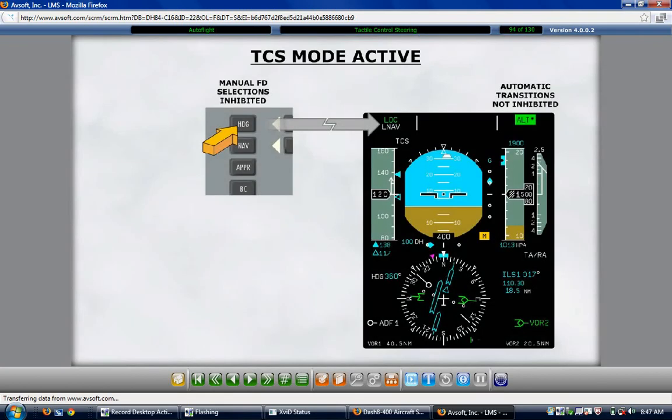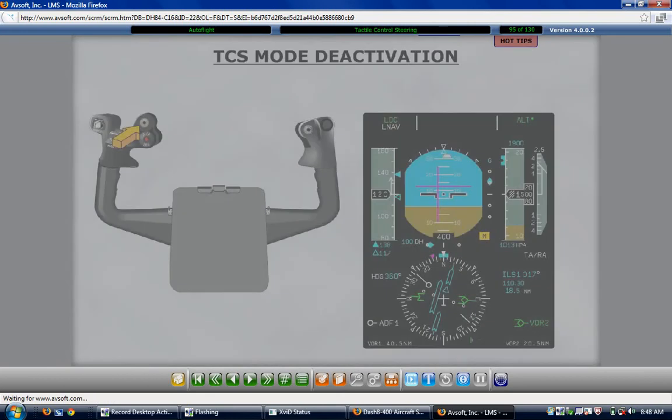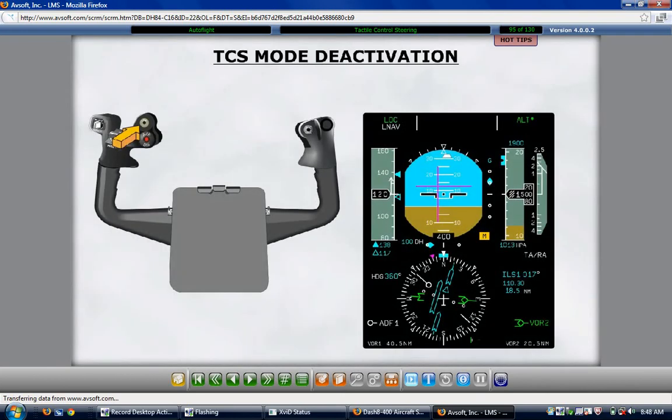The autopilot couples the flight director commands to the flight control surfaces using pitch and roll servos. The autopilot is engaged by pressing the autopilot push button on the flight guidance control panel. An autopilot engagement automatically engages the yaw damper. If a failure prevents the yaw damper from engaging or disengages the yaw damper, then the autopilot also disengages. Press the autopilot push button to engage the autopilot and yaw damper.